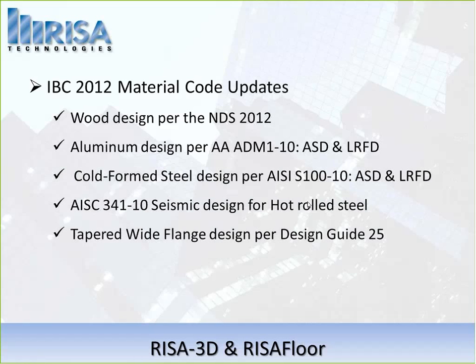A big one that people have been asking for years: we got the design guide from the folks at AISC, and so we implemented tapered wide flange design. This opens up a lot of doors for tapered design, and it's really nice to have in there. When we were looking at that, we had some time to work on enhancing the feature, so I want to show you how it works inside of RISA 3D. I'm going to show you an example.